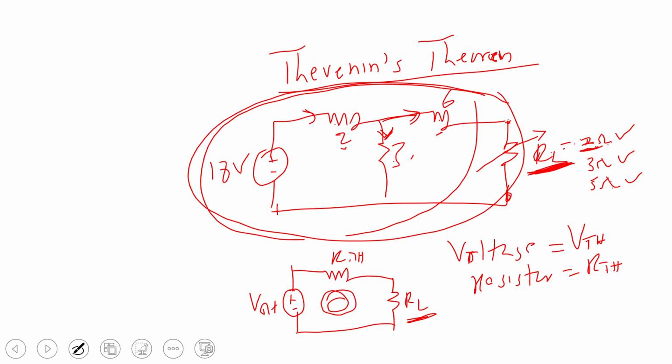So Thevenin says that for that particular bulb, just represent the terminal there where the bulb is. What it means is that first of all, you have to remove the bulb. Then when you remove the bulb, you are going to represent the terminal there as a voltage and a resistor.